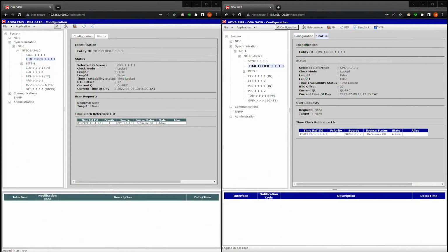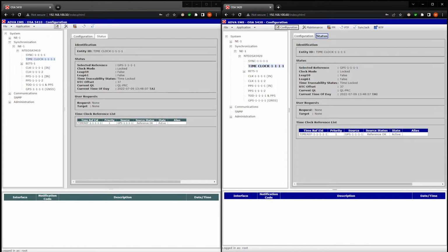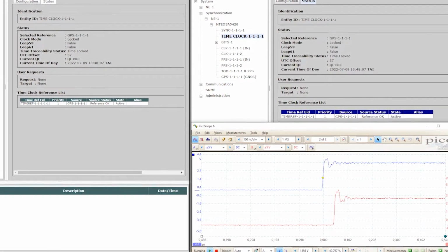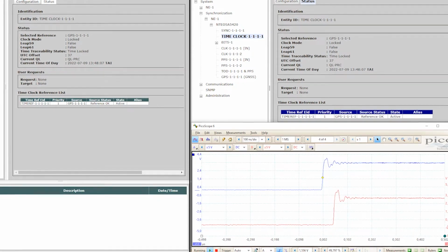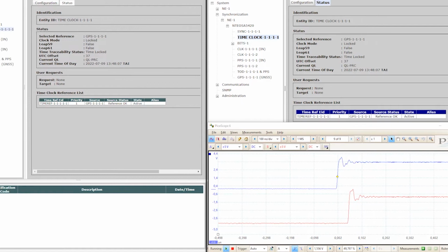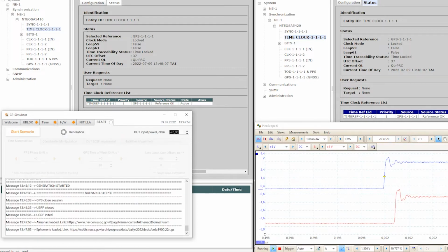This time I will launch a coherent attack, and then I will try to shift the phase of the PPS by 1 microsecond. Here you can see that the phase difference between the reference and the device under test is less than 50 nanoseconds. Let's now set the start delay to 0. Okay, great. And we don't need much power here. Let it be minus 110 dBm and launch.